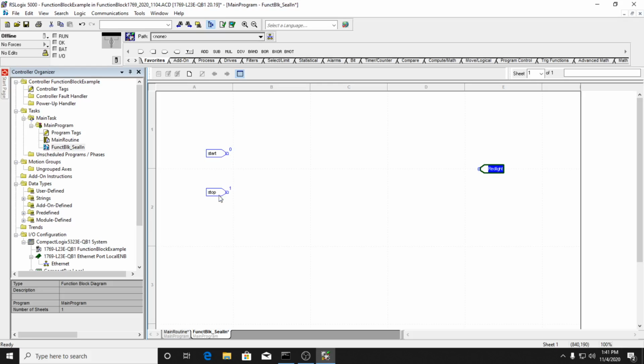And so you can also see it's actually telling you here that the stop button is a 1, because of course it's already pre-wired as a 1, or closed. So a 1 indicates that that switch is closed. A 0 indicates that the switch is open. And so now I'm going to select a B OR bit or box here. So this is a function block. In this case, it's simply an OR.